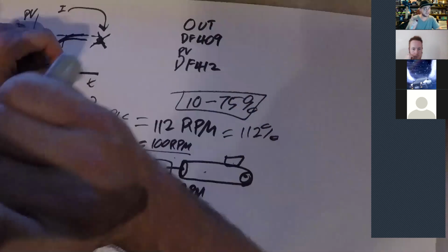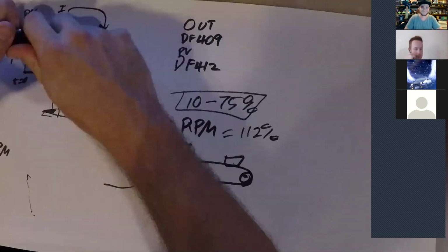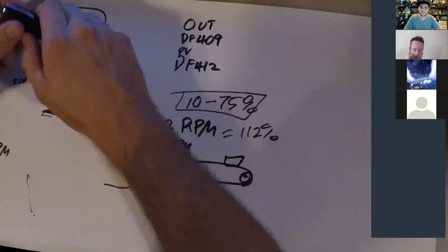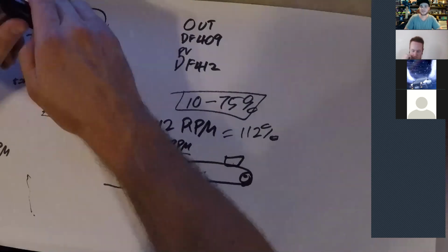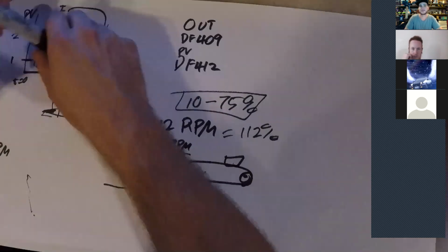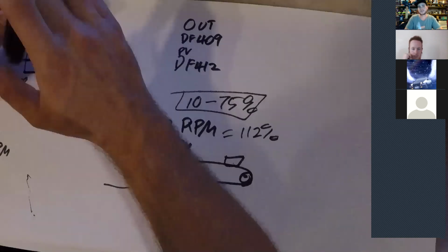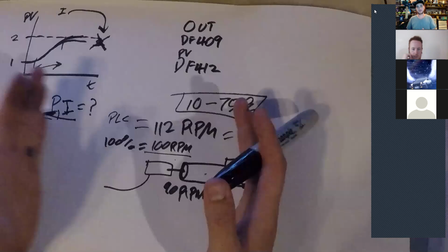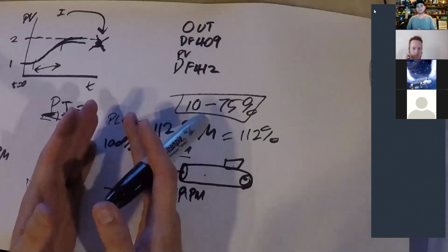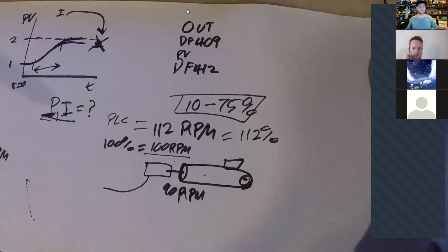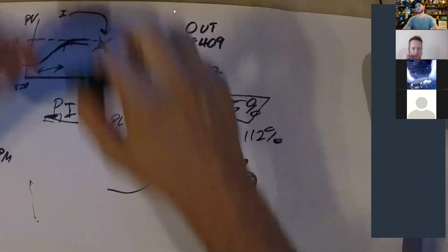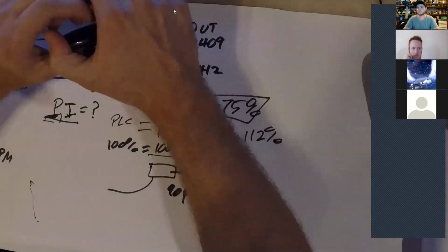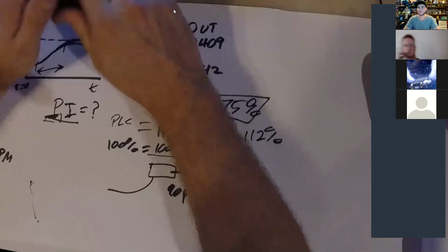And it has yet to be tested. I'm pretty confident this will work unless I goofed up something on the scaling. And that's why I made such a big stink about making sure your process variable and your set point are apples to apples, because if they're different units or something, this will explode. Hopefully in a fun way and not a physically damaging way.